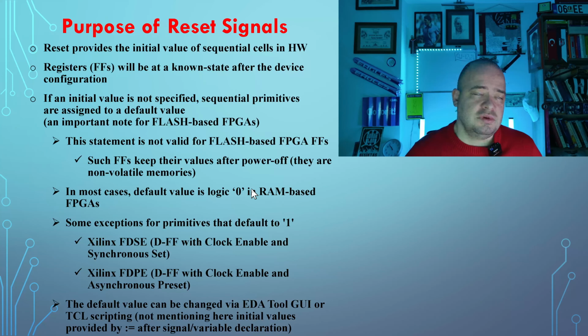So writing, actually providing, an asynchronous reset or synchronous reset statement is, of course, not enough. You need to have those signals physically resetting your flip-flops, so they need to be there physically.